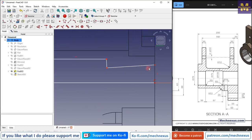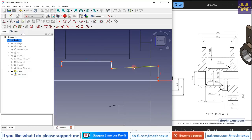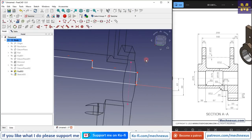Now here if you see, this point is not attached and this line is not horizontal, so first we will make it horizontal, and we will project this edge, and here I will select this point and line and add a coincidence.